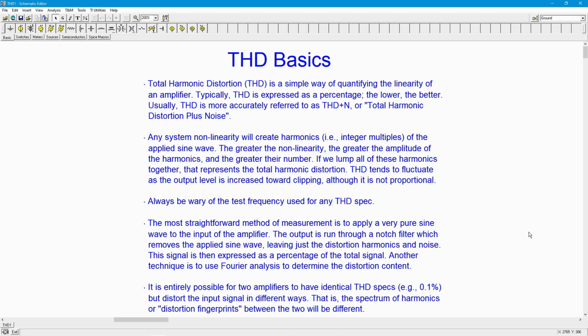And then you would get a distortion analyzer. You'd set up your stuff. The distortion analyzer would include inside of it an adjustable notch filter. And if you had a nice one, I remember we had an HP, there was a little switch on there and it would automatically tune the filter for best result.